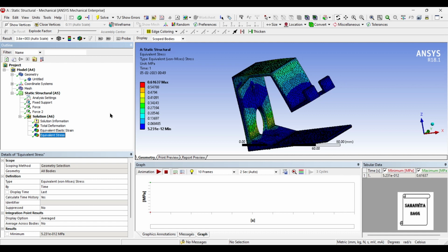Though stainless steel will not be a good choice, the reason being it will be a little heavy in weight. So if you take up aluminium alloy, it will be resistant to corrosion. Also, it will be light in weight and cheaper. So if at all you have to decide between the material, you should take up aluminium alloy as the choice.